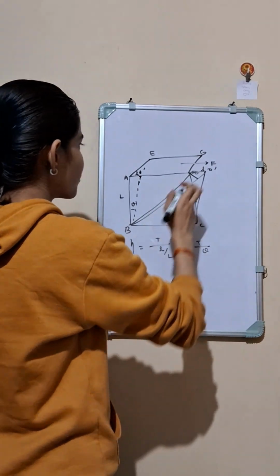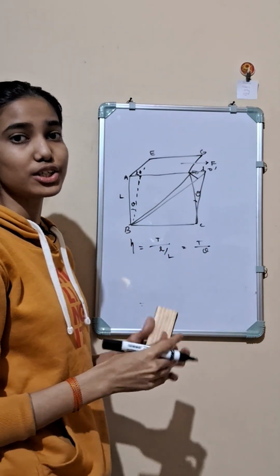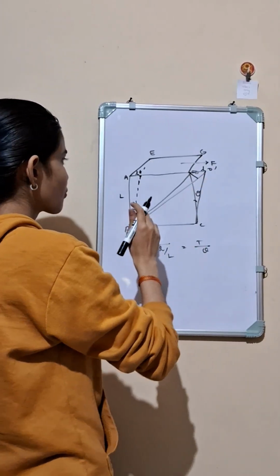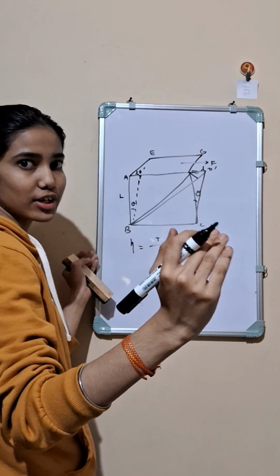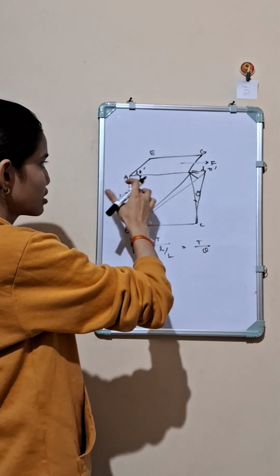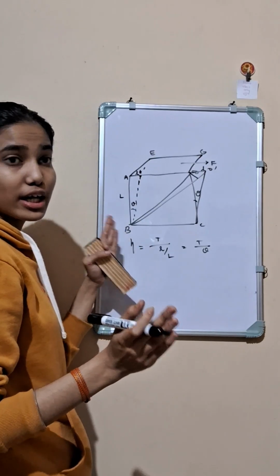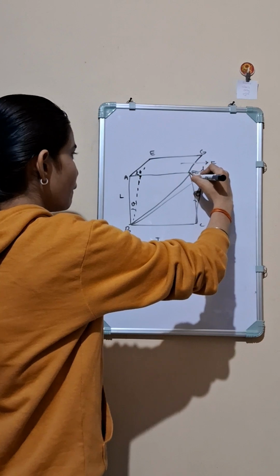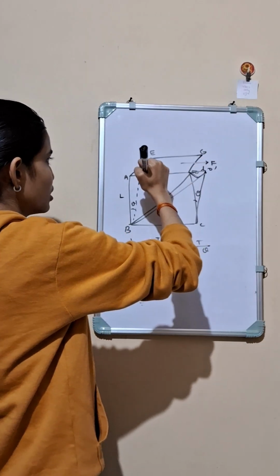Now we know that tensile stress along BD is equivalent to shearing stress along the upper surface. So a tensile stress will be there, and therefore a linear strain alpha will be there, and also a stress is acting along the diagonal AC, which is contracting AC. Here you can see that BD dash is longer than BD, but AC dash is smaller than AC.